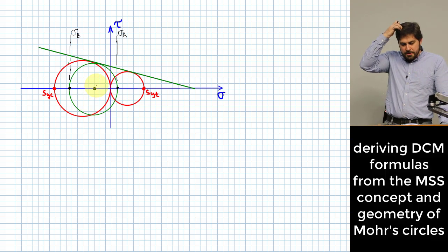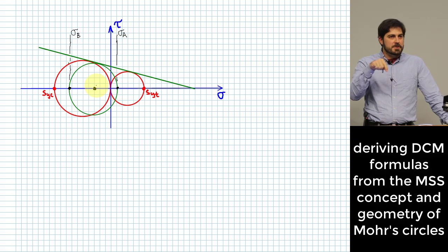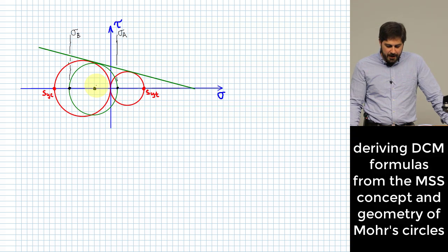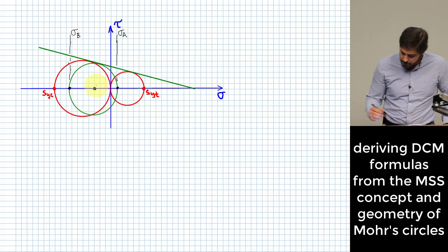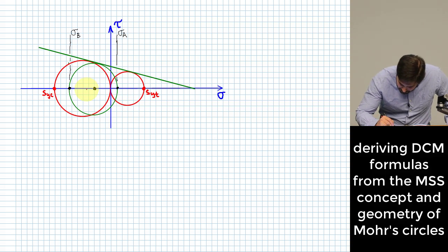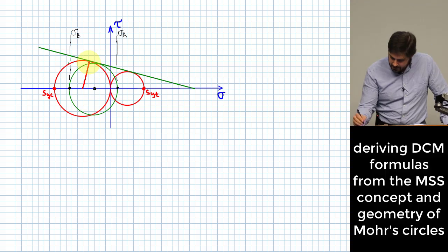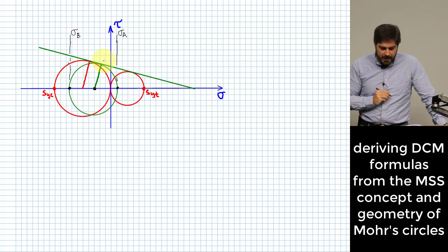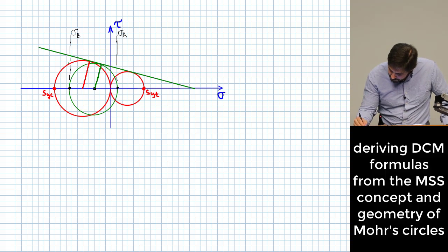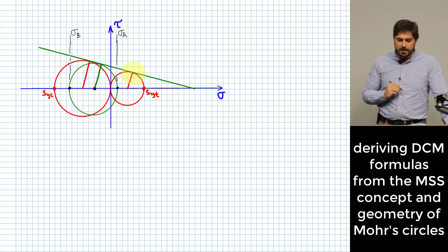We can also do some interesting things here where we identify radial lines for each of these Mohr circles that I have here and show those radial lines extending up to that tangent line that goes relative to those circles. All right, so let me do that. For this circle right here, there would be a line that extends up like this. I'll do it in a different color here for this one. There's a line that extends up like this for that circle. And there's another line that extends up for the tensile case up to that other line.